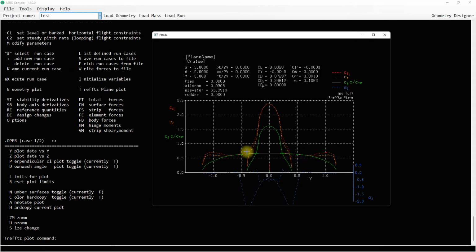If you see that you do not have the continuous lift distribution, it may be because in your definition of the geometry file, you did not properly distribute the span-wise and chord-wise length for your lattice or grid. So maybe you should go back and check those. And that should be able to fix the distribution to be more continuous rather than discrete or discontinuous.